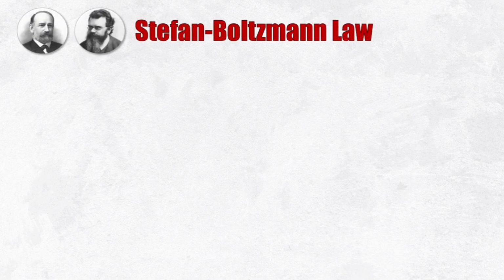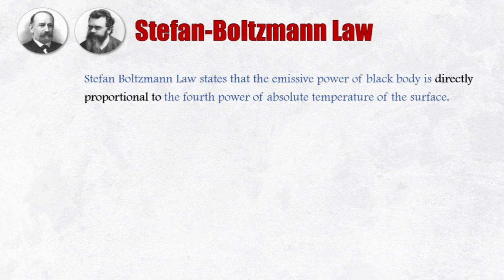Now we will discuss the Stefan Boltzmann law. Stefan Boltzmann law is the most important law in radiation. It governs the radiation heat transfer. According to Stefan Boltzmann law, the emissive power of a black body is directly proportional to the fourth power of the absolute temperature of the surface. For example, if any black surface is at 1000 Kelvin temperature, the emissive power of that black body will be directly proportional to the fourth power of 1000 Kelvin.